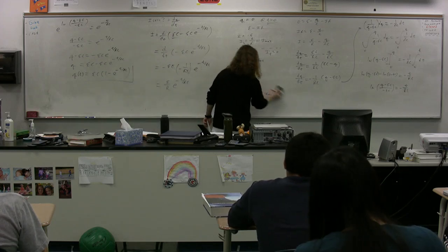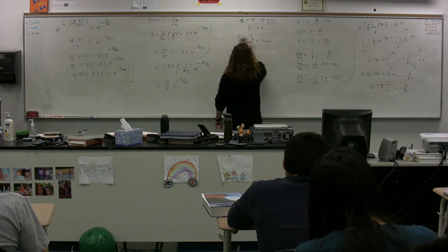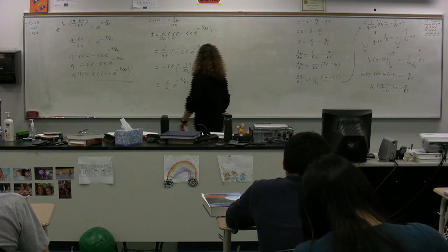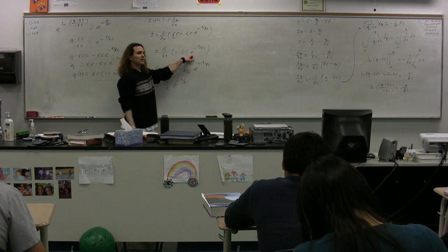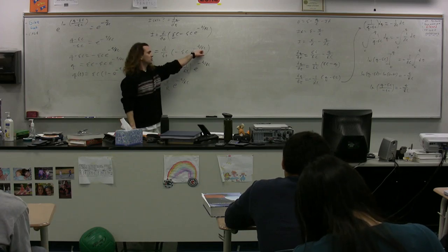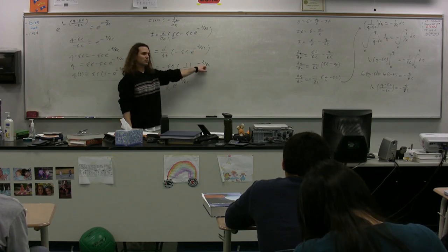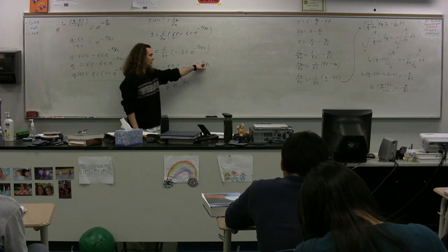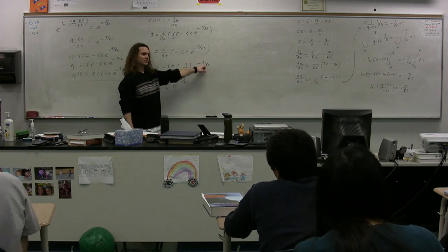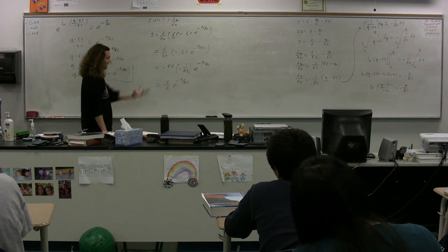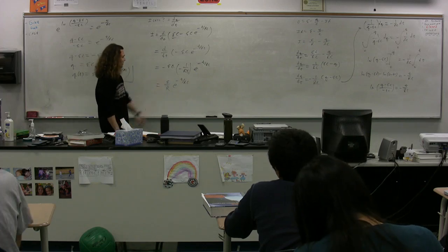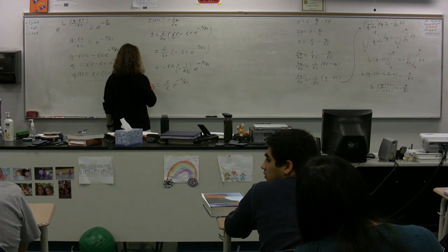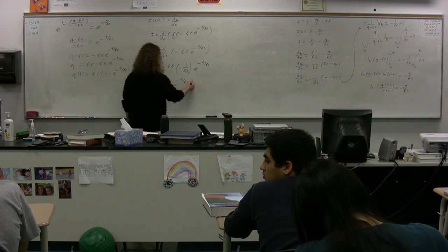Can you go over that last part? Sure. The derivative of e to a power is just, you multiply through by the derivative of the exponent and remain with the e to the negative. Why does it have a t? Because it's the derivative of this, which is just going to be negative 1 over RC. So we end up with the EMF over the resistance. So this is the current as a function of time.